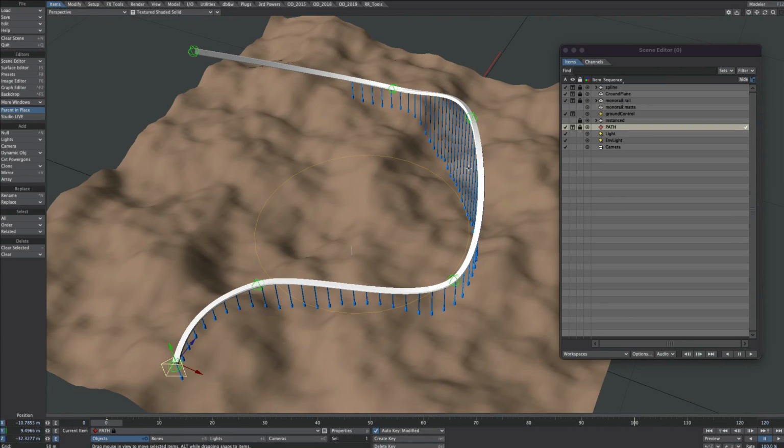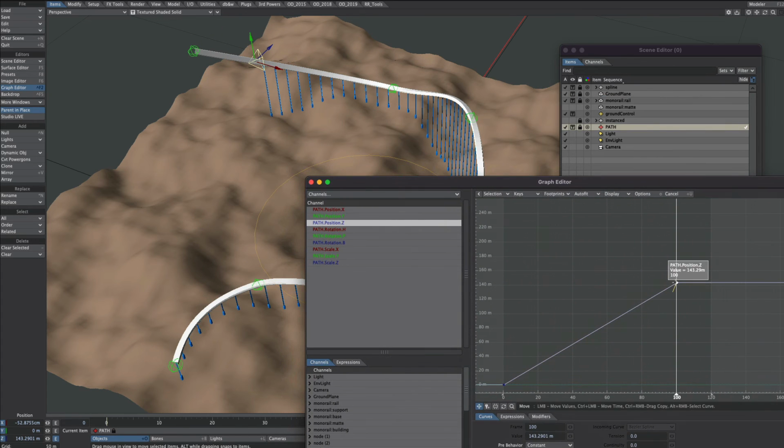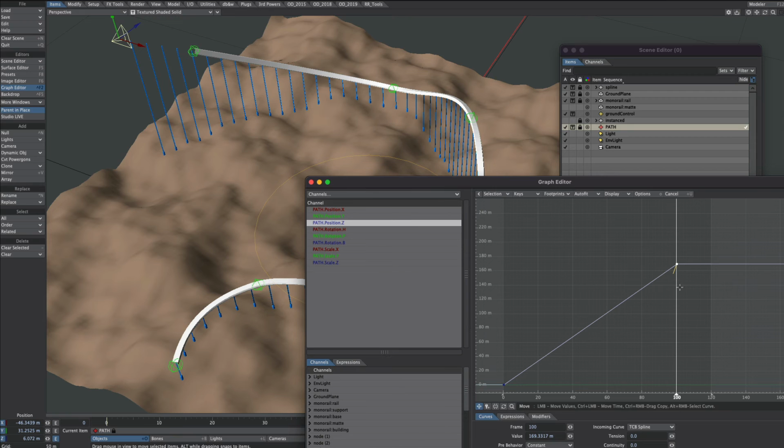This wouldn't be LightWave without mentioning a couple of limitations. Let's begin with this path. Now there's no way to calculate the length of this spline, unfortunately. So if this spline gets longer, you're going to have to estimate the end point. So you could either do that grabbing the handle along the Z, or you could just go into the graph editor if that's causing you problems and extend that way.